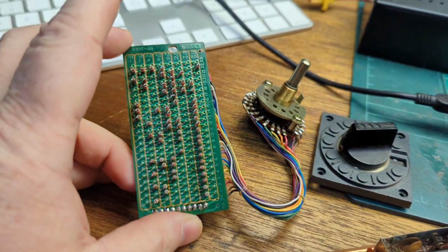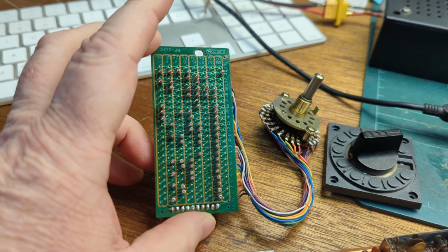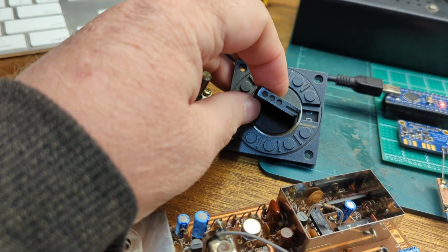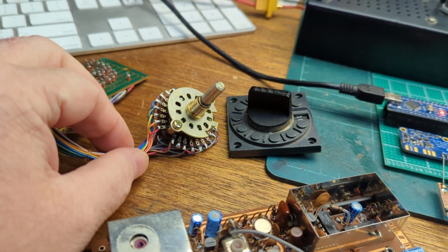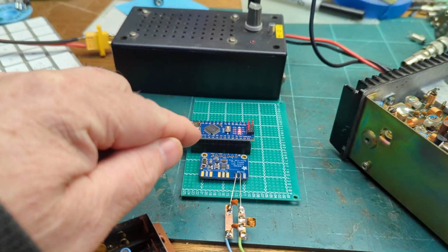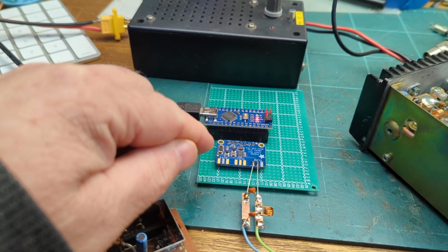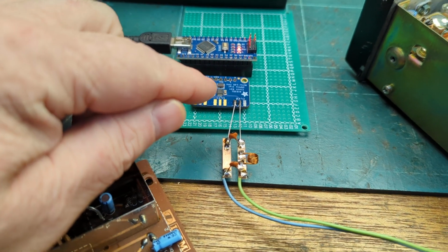Here's the diode board for setting the frequencies before. And this actual switch arrangement, which is the dial here, is actually a lot better for me when I want to plug it into this thing, which is a cheap old Arduino Nano. Here's an SI5351 that's doing the actual LO, so it's generating